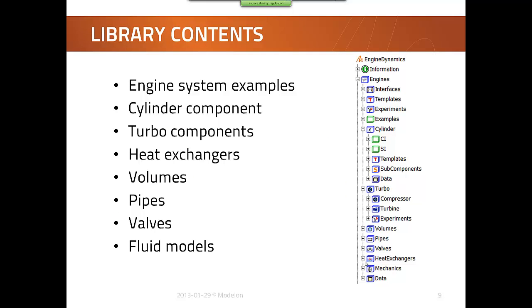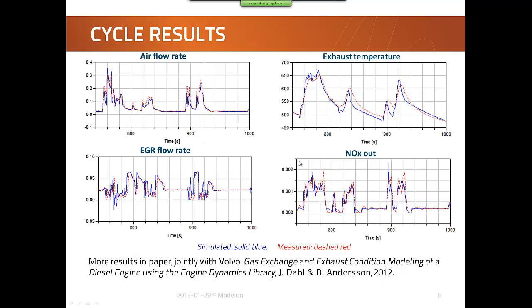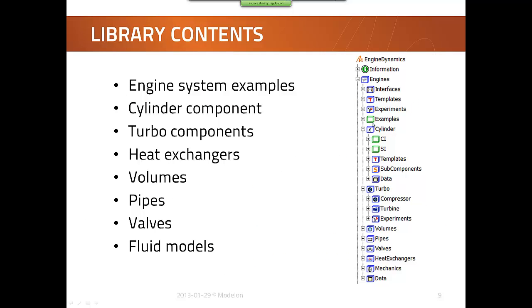So looking more at the contents of the library, we have an engines package which has a number of templates for engine system models. There are also packages for different engine components, such as the cylinder, the turbo system, and then general types of fluid components like volumes and pipes, valves, and simple heat exchangers.